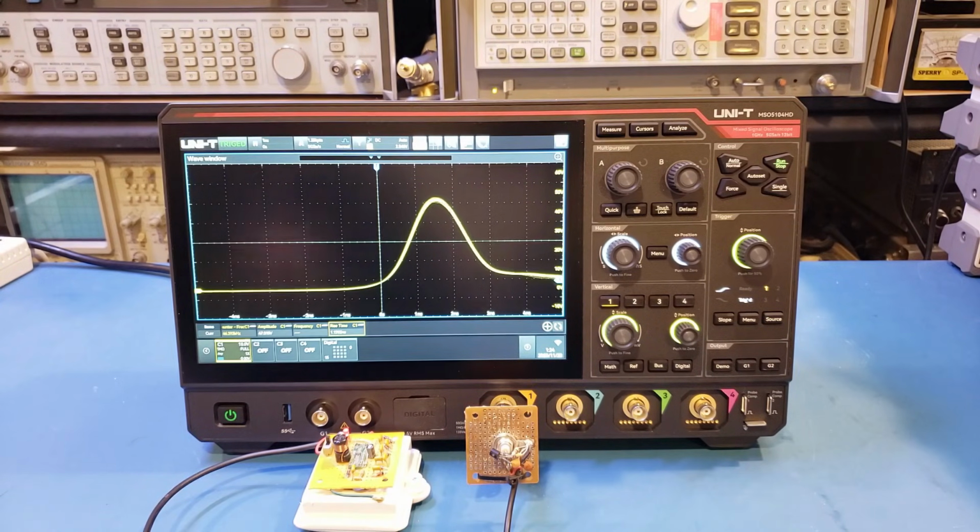Now, a good Avalanche pulse generator can probably output pulses much faster than that. So at some point, I may need to tweak the design of the Avalanche pulse generator a little bit. In theory, I should be able to reduce the rise time to probably about 300 to 500 picoseconds with better components and probably more careful layout.